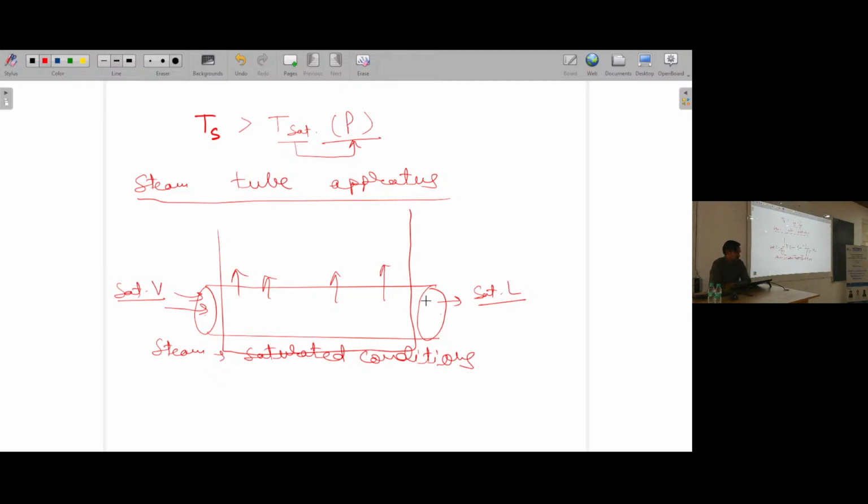then the temperature from this point to this point will remain almost close to the surface temperature. Now, outside, we need to use the working fluid which has a boiling point equal to the saturation temperature of this steam at the given pressure condition. Many of these experiments are done with organic fluids, because typically at atmospheric pressure their boiling point was less. And this is how the constant temperature regime, some of the data points were obtained